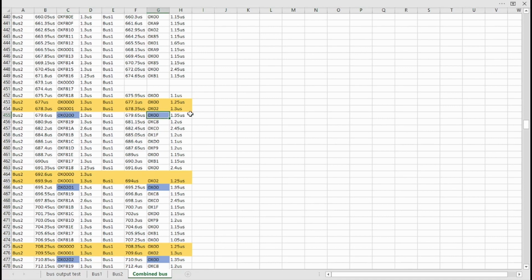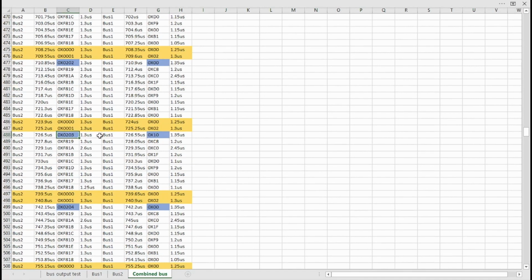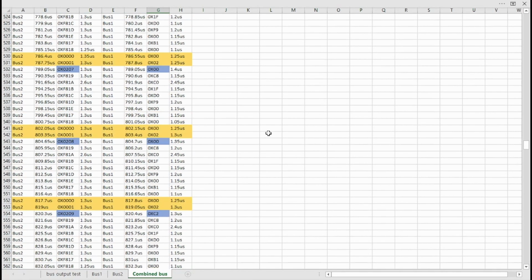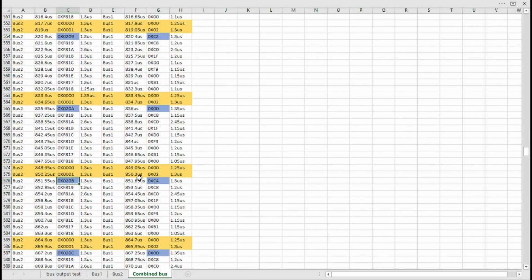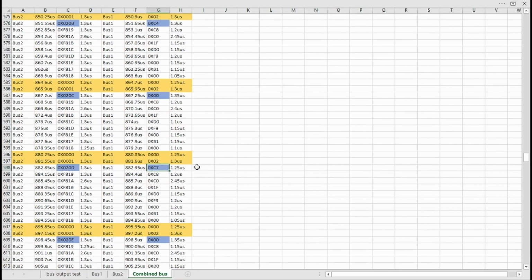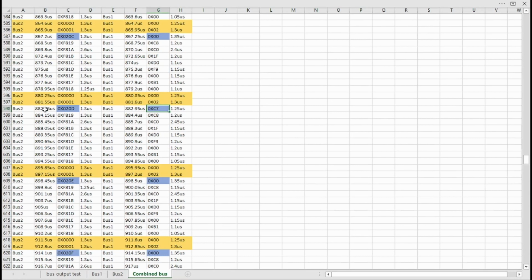So we have highlighted in blue the values so we can see them easier. So the first one of use we expect to be 0203, and sure enough we have our 10, 0209 is the next one, C2, then we've got 020B is C4. So as you can see, we are indeed reading exactly what we should have from the RAM. So we've managed to write to the RAM, and now we're checking the RAM and it's checking out fine.